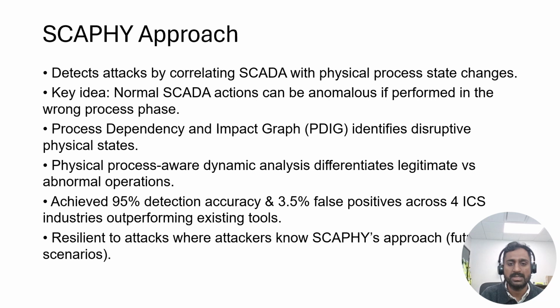One of those is called the process dependency and impact graph, which identifies disruptive processes and physical states. And they also do process-aware dynamic analysis, which, as I mentioned, differentiates legitimate versus abnormal-looking commands from SCADA. And in their test, they've achieved 95% detection accuracy in a test bench scenario, and they had very few false positives across different industries. And they found that they're resilient to attacks where attackers might already know Scaphy's approach.